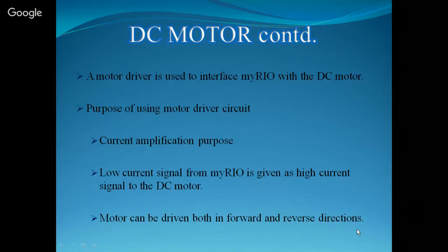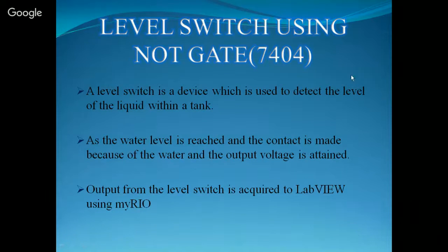Next, level switch. The level switch is used to detect the level of liquid in a tank. We have designed a circuit for level switch using NOT gate IC7404. It detects the level of water in the mixing tank for our project.